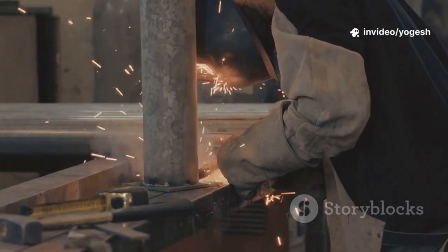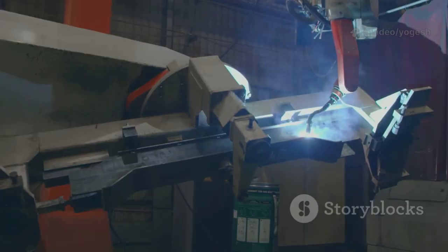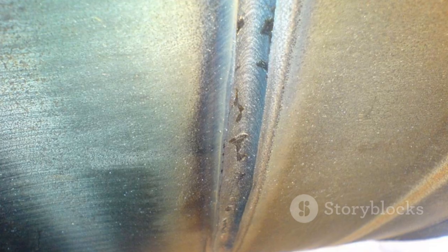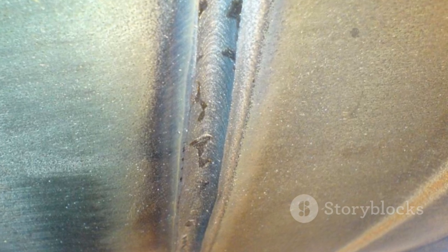Not all welds are continuous. Intermittent welds save time and material while providing needed strength. Specify them by placing segment length and pitch to the right of the weld symbol, e.g., 2 to 6 means 2-inch welds every 6 inches.